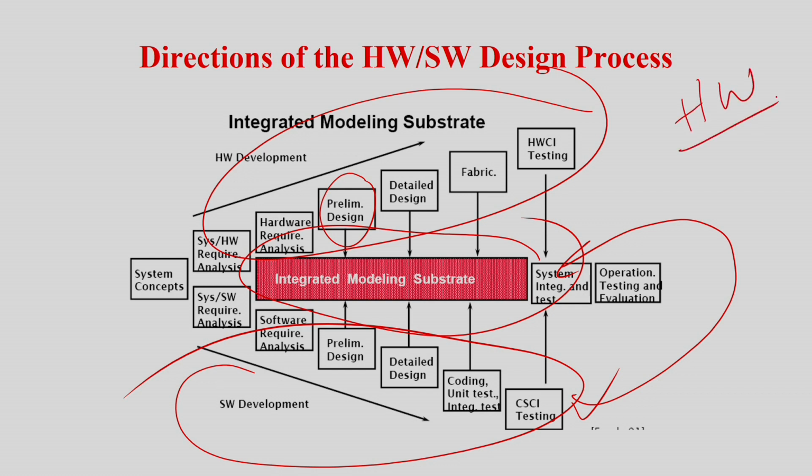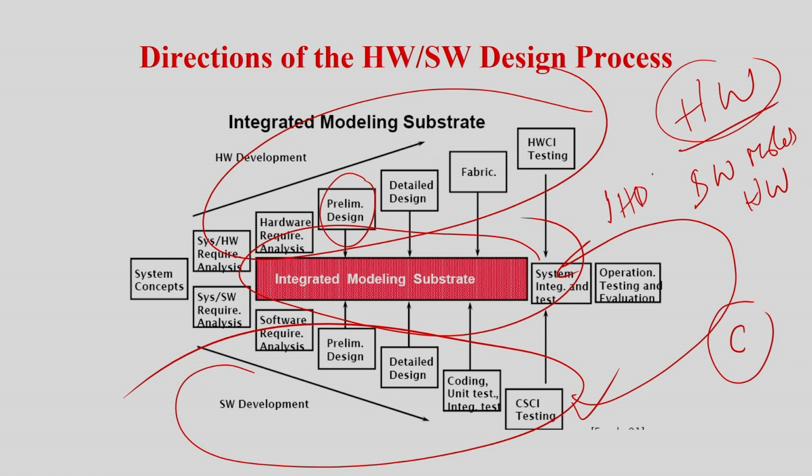Verilog and VHDL are all software representations or software models of the hardware. And we have some C code or Java code which I am going to execute on this hardware. So these hardware simulators are for pure hardware. We have some hardware models which run in software like Verilog and VHDL. VHDL basically models this hardware which is written in a soft language. But VHDL cannot simulate this hardware with this C language. Those things are not available, or even if they are, they take a long time to simulate.